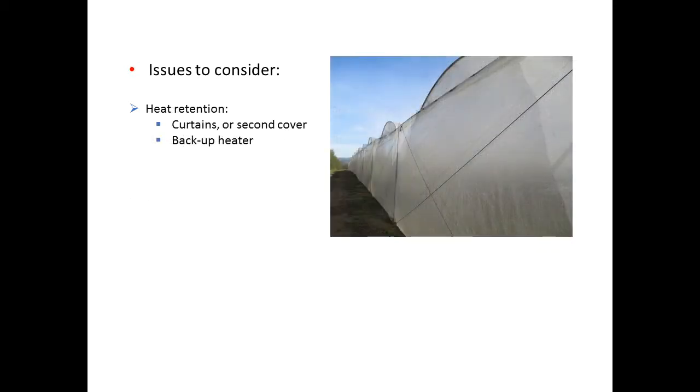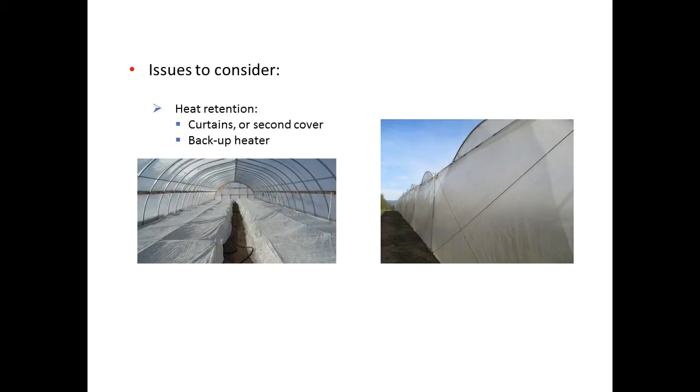Obviously, we are concerned about heat retention, and that has to do with ventilation to a certain extent, because as we are trying to ventilate, we want to be careful that we don't ventilate out any heat that we want to keep inside the structure for when it gets colder at night or during a cold day. So we can use some tricks.